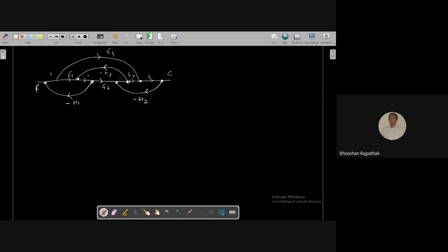Okay, this is the signal flow graph. Now, in this signal flow graph, these are the two nodes in between which the gain is 1. Similarly, between this, gain is 1, gain is 1, gain is 1. In this kind of thing, the simplification you can do is shift these nodes here if the gain is 1. Okay, there is no gain there. So this graph is equivalent to the graph which I will draw now.